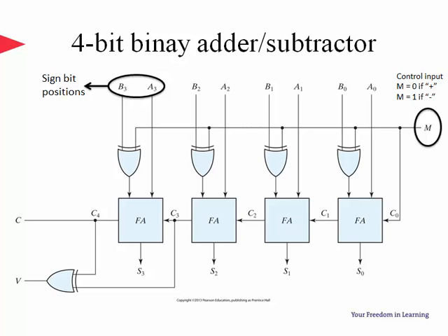If both are positive, for overflow C3 must be 1. And since A3 and B3 are zeros, unsigned, the carry C4 is 0. Thus, V, which is another variable that helps detect the overflow, is 1, meaning that there is an overflow.